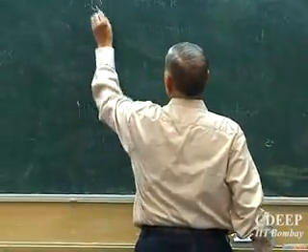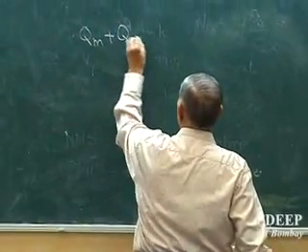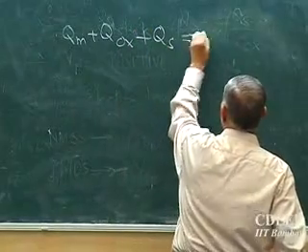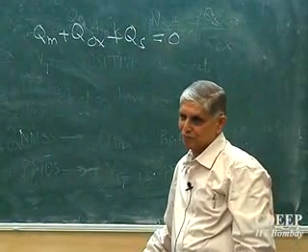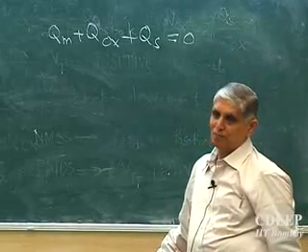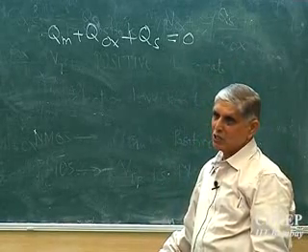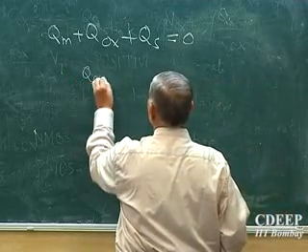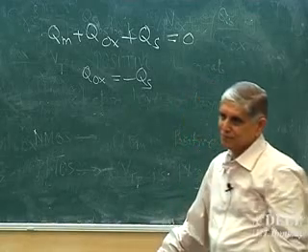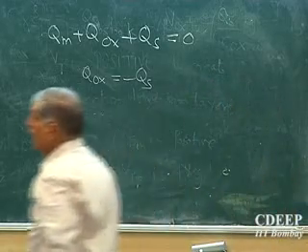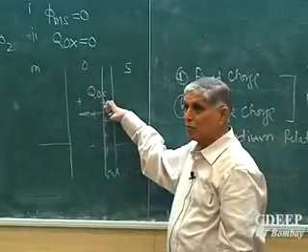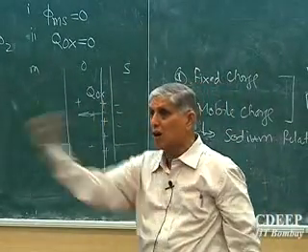The Gauss's law said Qm plus Qox plus Qs is 0. Is that correct? And I have not applied Qm. I have not applied Qm. So Qox is minus Qs. What does that mean? If I put a positive charge at this side of the interface, negative charges must appear across for the field to terminate there. Is that correct? This means what has happened, without applying voltage, electrons or negative charge started appearing in the semiconductor.